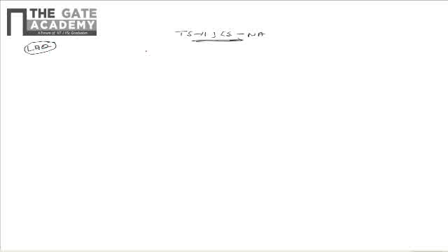As per the question, the open loop transfer function of a unity negative feedback control system is given as G(s)H(s) = 1/(s+1)^2. We need to find the Nyquist plot of this control system. So for finding the Nyquist plot of the control system, let us substitute s = jω.